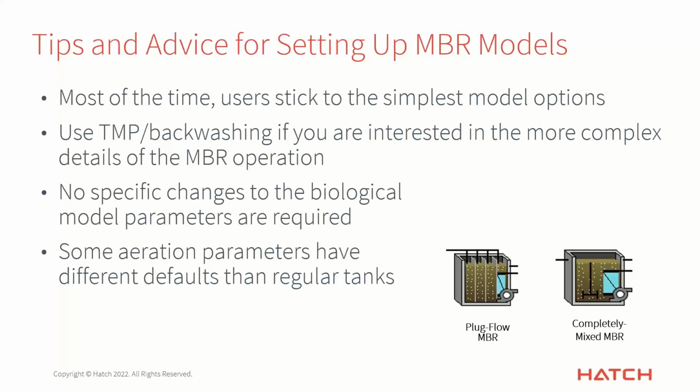But one thing that is different is that some of the default parameters in the aeration model are different in the MBR than they are for regular tanks. You'll find that alpha is different and the oxygen transfer is different. You'll also find different values for the regular biological air versus the scouring and cleaning air. We took quite a bit of effort to do that. I think we also tuned the DO controllers a little differently, to keep it a little more realistic for the types of technologies that are going to be used for those two particular purposes.